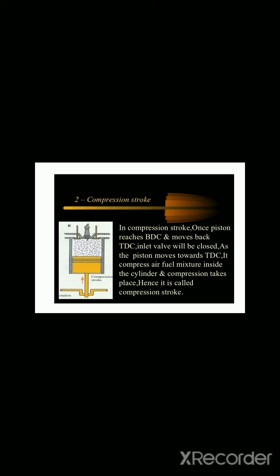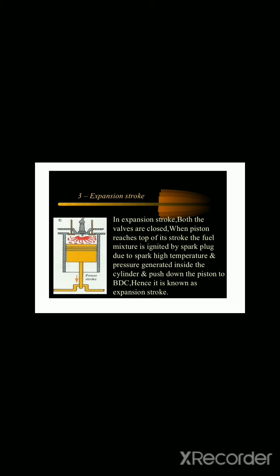Compression stroke. In the compression stroke, once the piston reaches BDC and moves back toward TDC, the inlet valve is closed. As the piston moves towards TDC, it compresses the air-fuel mixture inside the cylinder and compression takes place, hence it is called compression stroke. Third, expansion stroke.